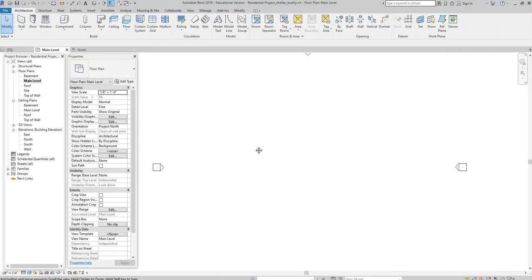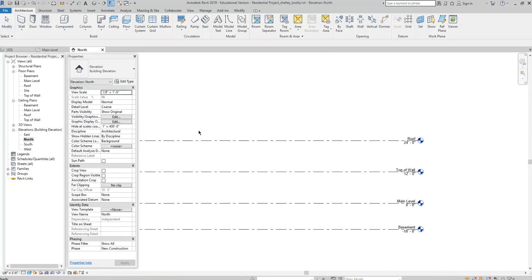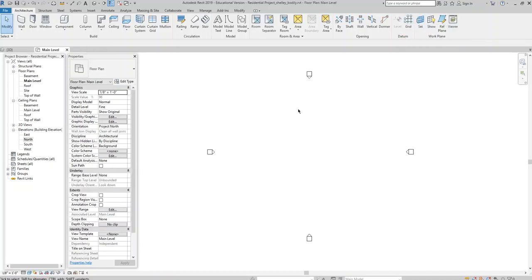And we can create a grid in a floor plan view. Or an elevation view. I guess I've just never done that before. I think probably I've never done that before because it makes sense to draw a structural grid in floor plan view, right? But a structural grid, or if it's not a structural grid, whatever type of grid that helps you organize your architecture, whatever you're drawing, is always very helpful, right? So I want to show you how to add grids.